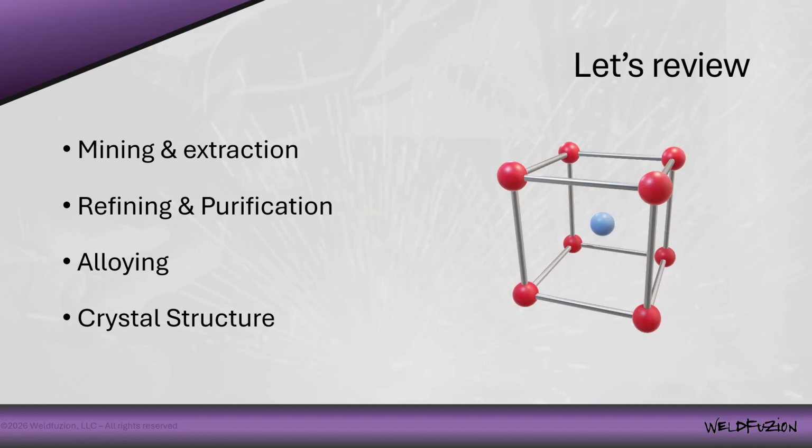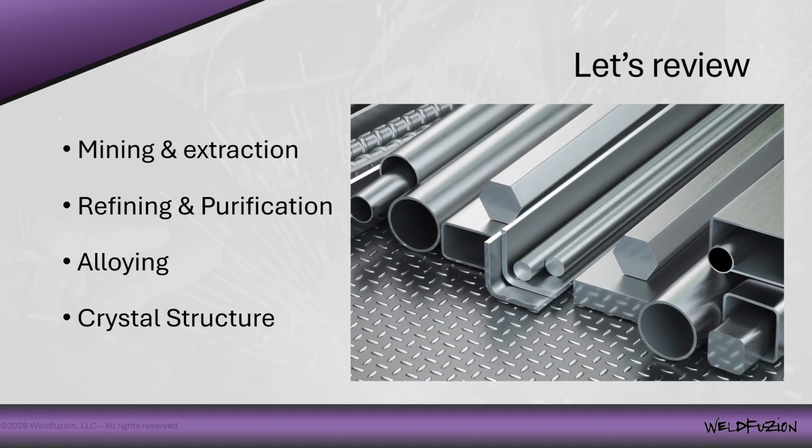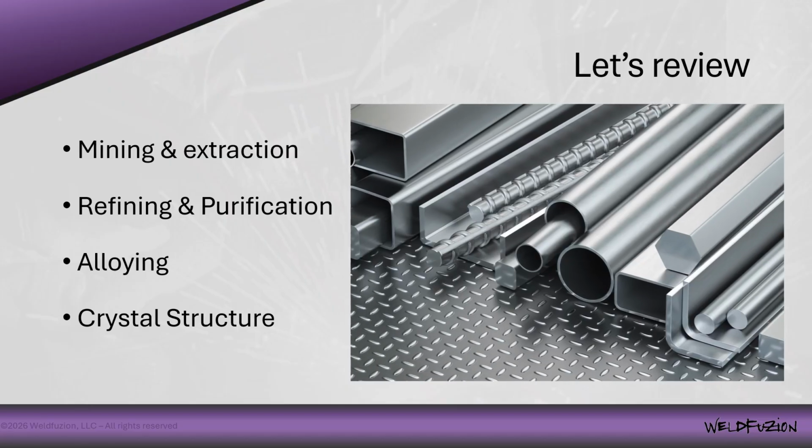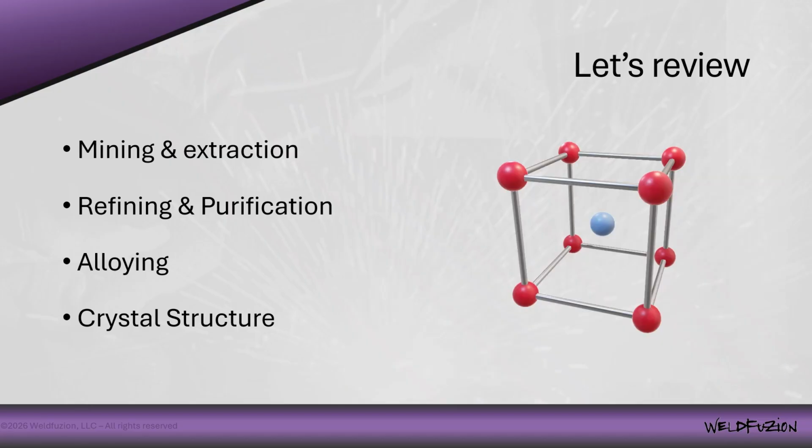Even the term aluminum could be referring to hundreds of specific alloys with a matrix of heat-treatable and non-heat treatable varieties. As we mentioned before, all metals form a crystal structure upon solidification. Based on the relationship to other elements, atoms, or molecules in the mixture, they'll take on a certain orientation. This crystal structure is very dependent on the heating and cooling cycles that the material's gone through from production to processing.